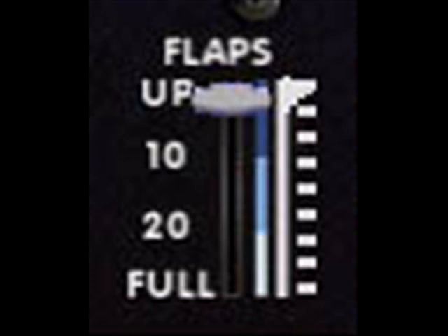Here's how the process might go if you're too high and need to add flaps to compensate. Since the full flap stalling speed for the airplane is 40 knots, that's where the white arc begins on the airspeed indicator, you'll want to approach at a slightly slower speed. Remember, pilots use an approach speed that's 30% above the stall speed for the airplane's present configuration. For this situation, let's use 60 knots.